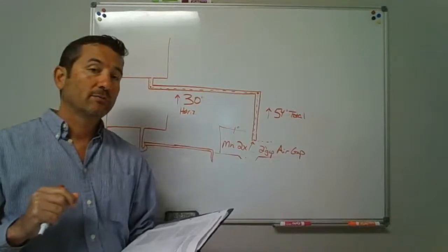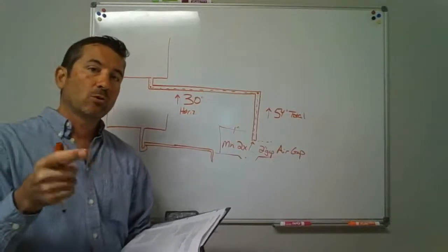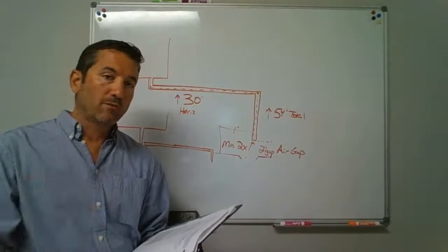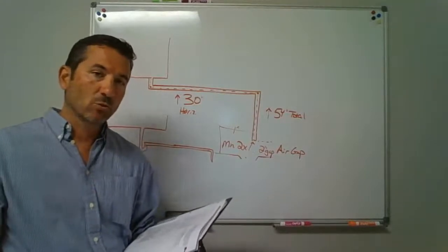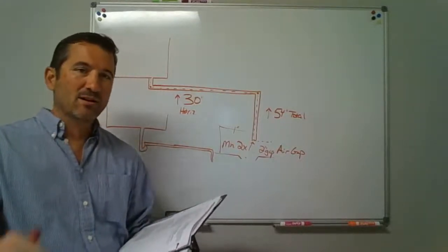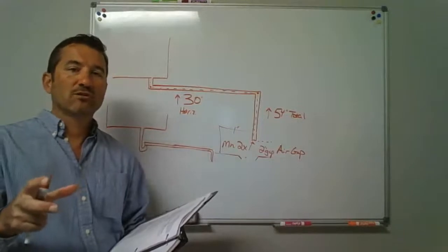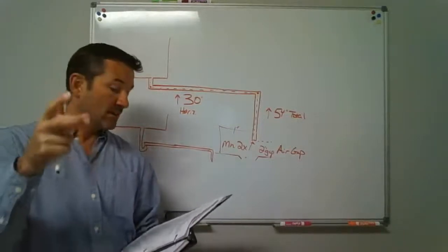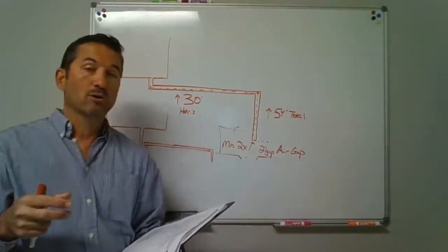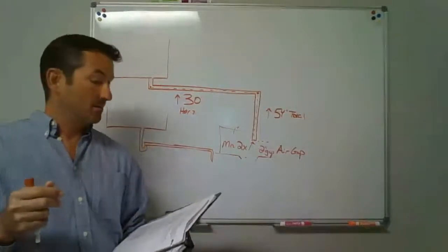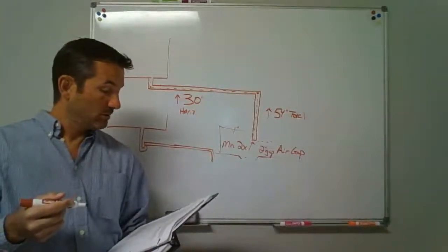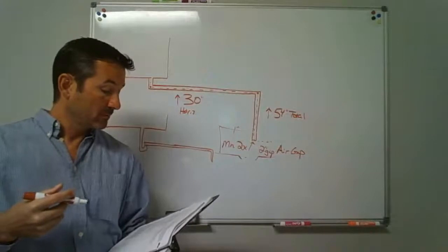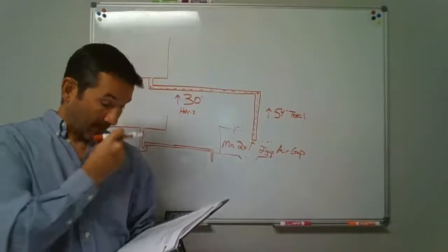So a hub drain is coming up above the floor because you don't want food and whatever's on the floor sweeping and just going down in there. It says you don't have to have a strainer on that. If it's coming up, you've got to be at least 1 inch above the floor, and it's a water impervious floor. Okay, standpipes.